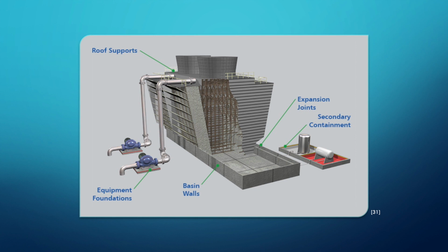Moving on to this diagram, you can see the bottom is that cold water basin where the splash fill and the water is drawn and goes into. The reason you want that water to go directly into the cold water basin and control the temperature there is because you can have a variable flow system, so you can control the flow rate going into it, and the pan heater can control the heat dissipation. I'm going to get more into that later on.